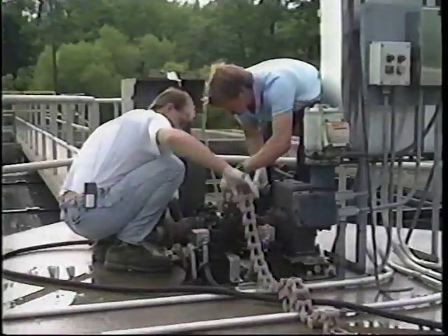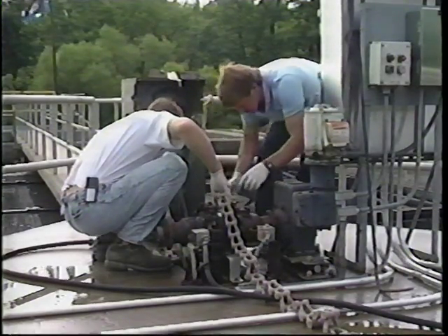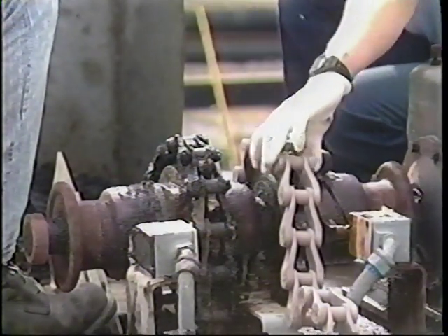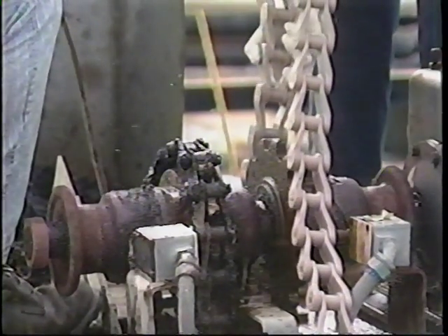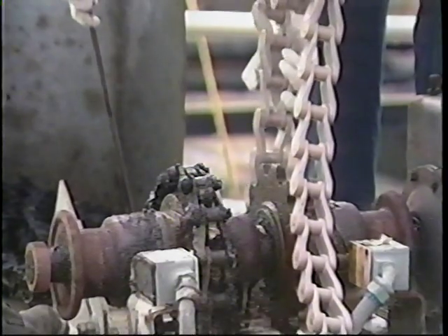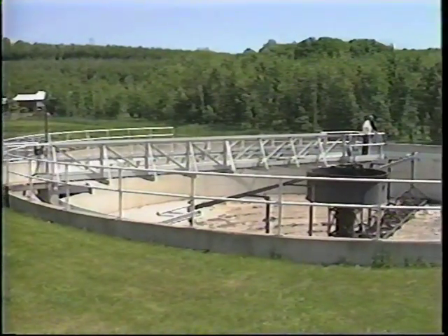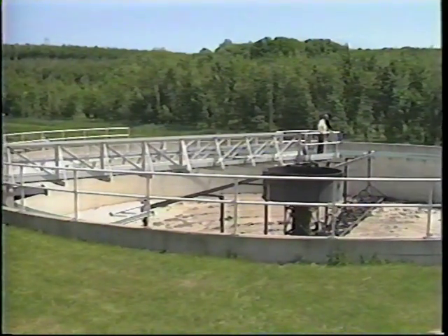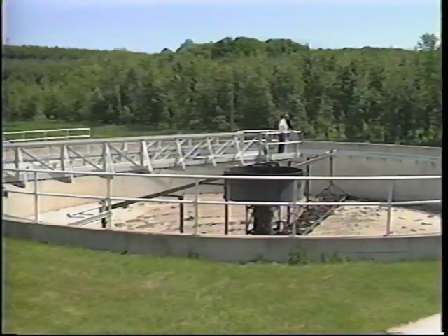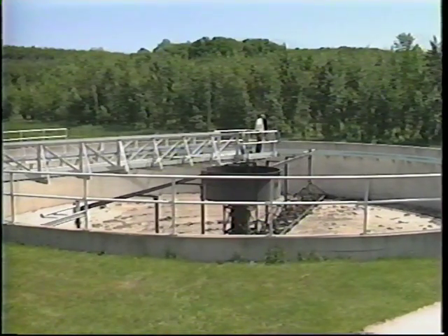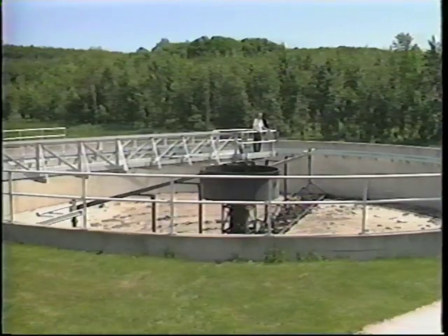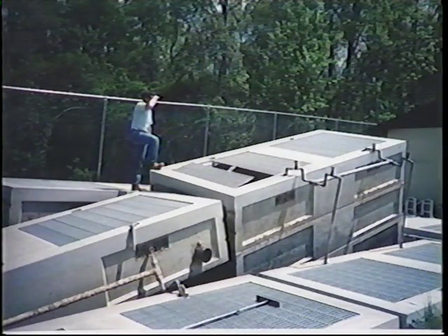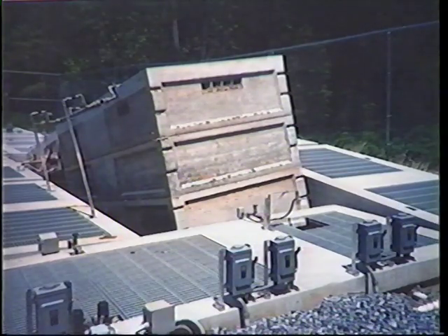Proper maintenance of the clarifiers is also a requirement of the NPDES permit. Please be sure to follow all manufacturers' recommendations for lubrication, inspections, and adjustment of clarifier components. Clarifiers must also be periodically dewatered or drained in order to inspect and adjust drive units and to inspect the tank structure and remove debris. Care needs to be taken when dewatering any tank because a high water table can cause tanks to float right